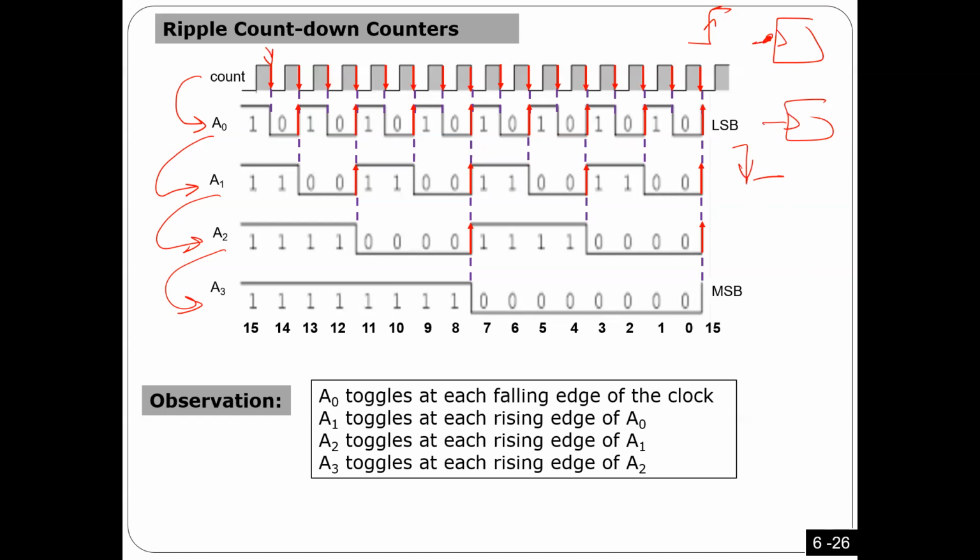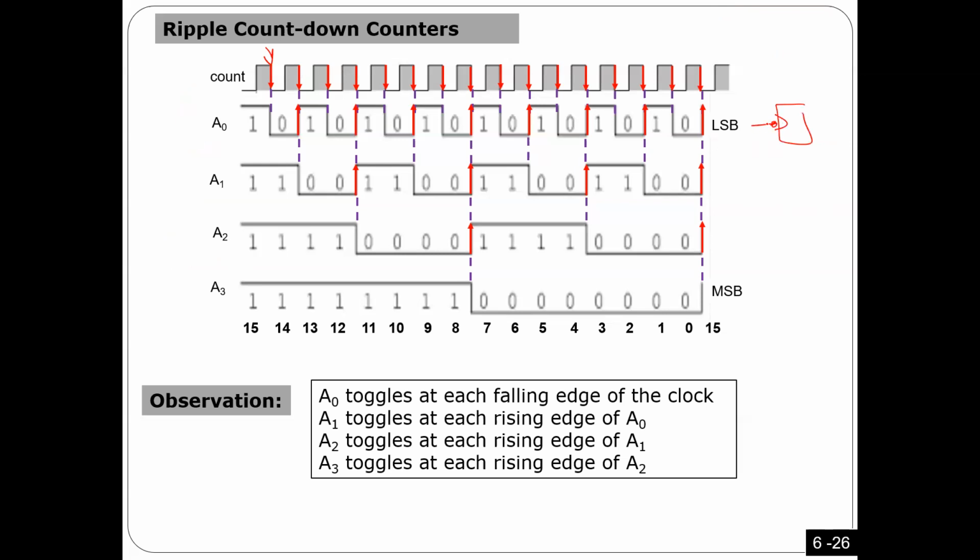So look how I'm gonna do it. All of them are gonna be triggered at falling, all of them. But how? Because this one has to be not at falling, but rising. Okay. Look what I'm gonna do. I'm gonna use 4 flip-flops, all of them at falling.